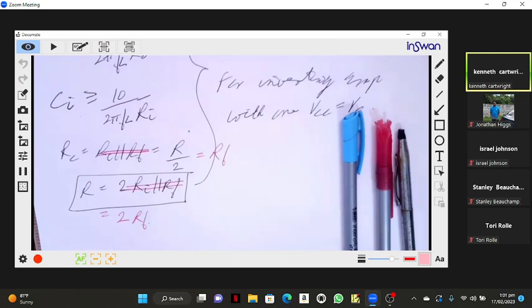I found out that you have to take out the comma and just write 3300 picofarad. Now that's something strange. I didn't even know that after all these years of doing PSpice. It took me a while when Mr. Beauchamp sent me his design, and his design was right. I could tell that his design was right, but PSpice had given him wrong answers because of this strange property that PSpice has.